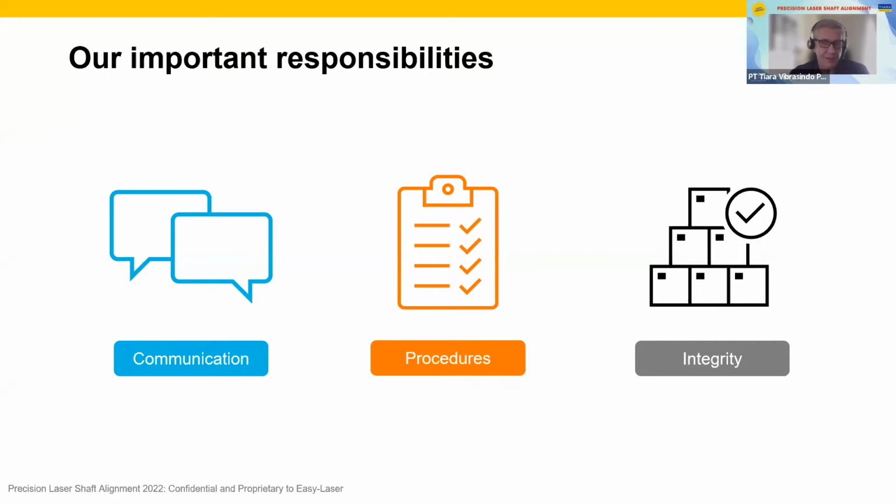But there should always be a reference to which specific standards all of those guidelines belong. They need to be on site, and it needs to be clear that the installation, for example, is taking place according to some API. The recommended practices for machine design, that is the API 686, are a perfect foundation where we could start. So there are many guidelines that exist to lean on or to apply.